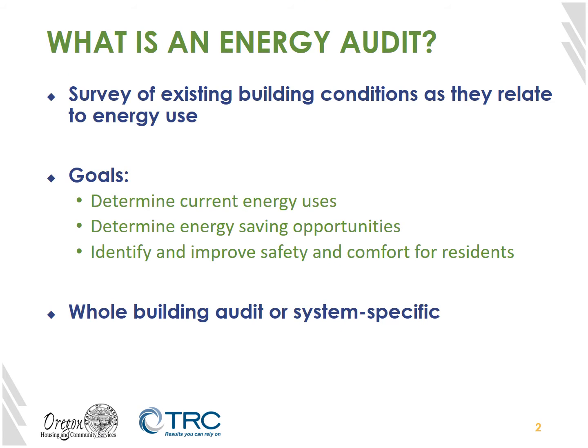The first aspect that we want to discuss is what is an energy audit of a multifamily building. It is a review of the existing building conditions within a building as they relate to energy use. The purpose of it is to determine current energy uses within the building, where the energy is being used, also to determine energy saving opportunities, whether that is in replacing systems or with fine-tuning the existing systems, and to identify and improve safety and comfort for residents.